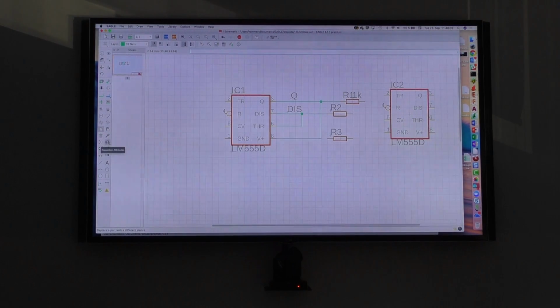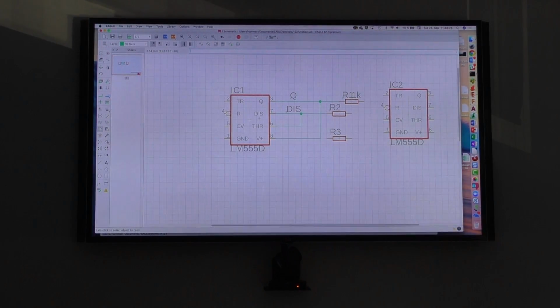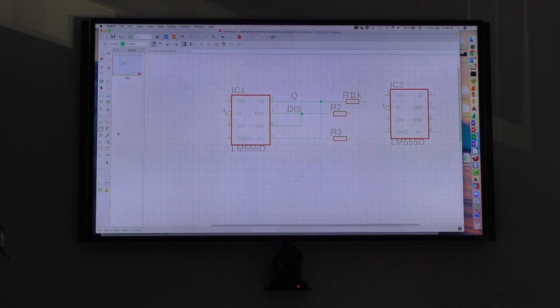Of course, I can delete something. I can replace something. If the guy who's doing the layout maybe says, hey, you selected here, I don't see it, but I see it's an LM555D. That means it's the surface mount device. I could already here change the package again. I change my mind and say, where's the package now? I lost it.